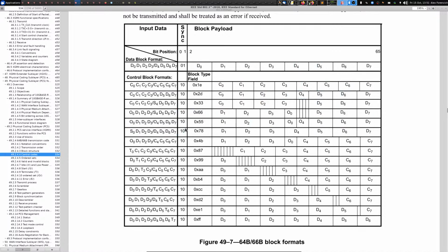Well, the first thing is you can look at the sync header, right? If you see a sync header of 00 or 11, well, then there's a problem. And currently the block lock synchronization components are looking at the sync header already. So obviously that's not sufficient, but it's a start. Another thing we can do is look at the contents of the actual data, right? Unfortunately, there's not much we can do for something that decodes as actual data, because you can send whatever arbitrary data that you want. So we can't validate anything based on the data.